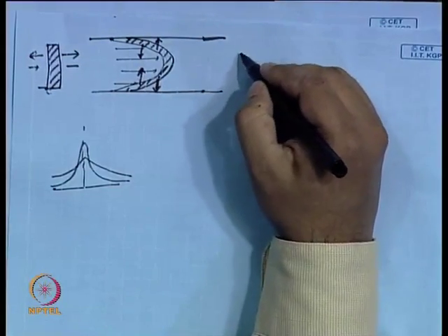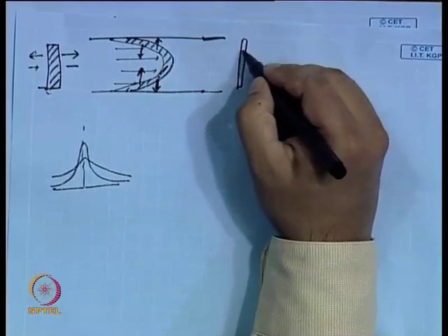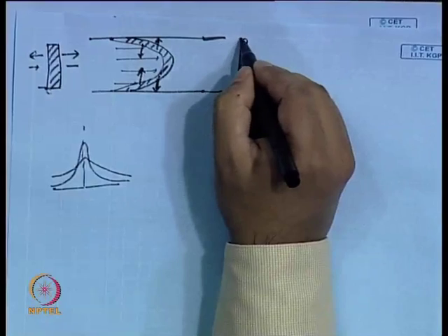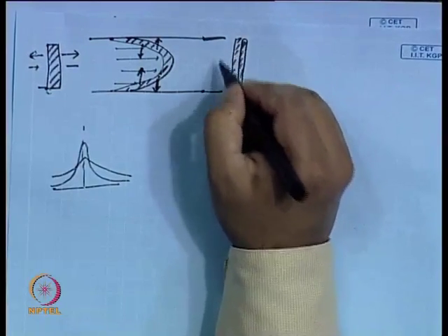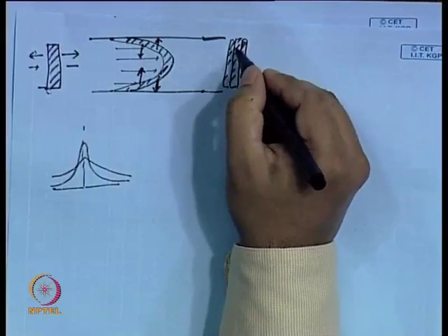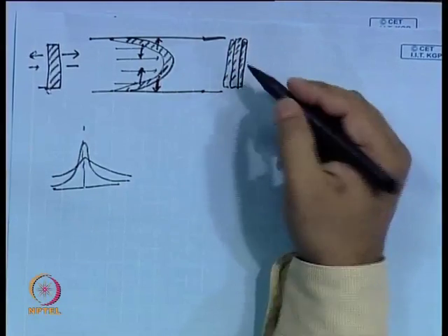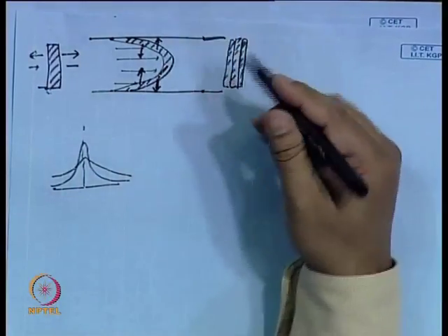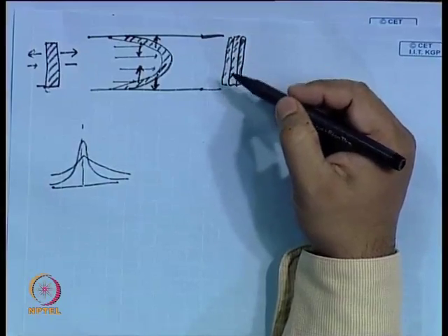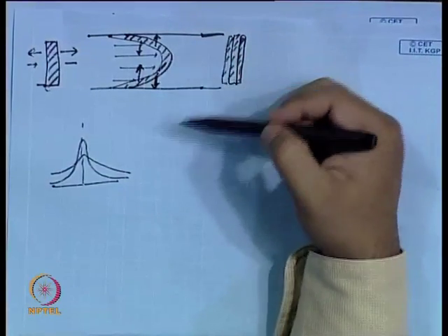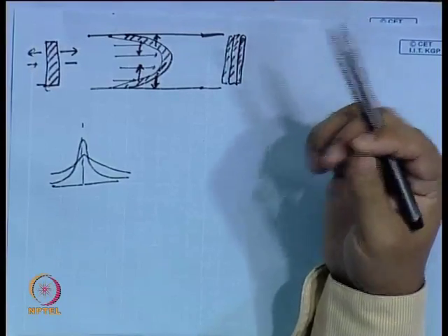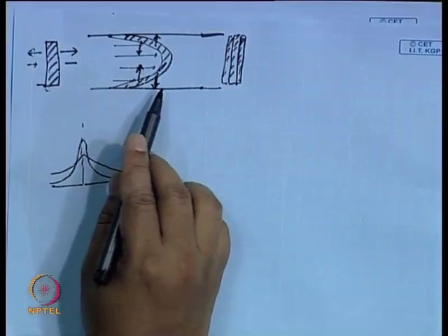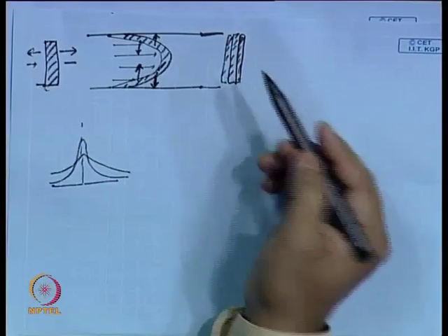Rather, at the outlet, you pick up a slice, measure the concentration, then you pick up the slice that you receive next and measure the concentration, which is basically the average over the entire cross section. This is called a mixing cup concentration. It is like you take that slice, mix it and get the average concentration. Suppose this is a thin capillary, and at most you can have an outlet connected to a detector. The detector would be detecting the average concentration of this entire cross section, that is all it can detect.